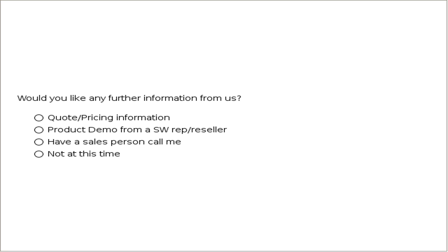Because as I mentioned earlier, when you mirror or pattern those items, each of the features get solved. So if you had a big pattern with 100 items in your pattern, 10 by 10, whatever, and each of those had maybe an up to next or an up to surface, each of those features get solved. With geometry pattern, they don't. So it can help with your performance. Mirroring a body is going to be very fast, because both doing the geometry pattern and mirroring a body are going to be fairly fast. So those are kind of on par.